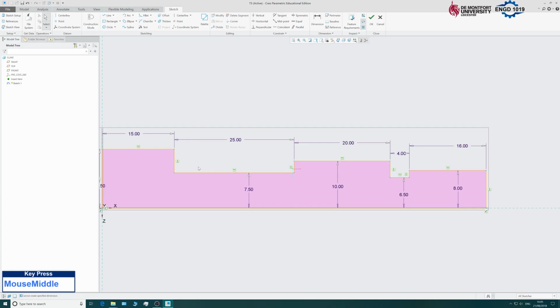So we've got a curved section that needs to have a radius of 20, and then we've got a sloped section down here. And so what's really useful is if we keep these lines here, because they're obviously giving us the overall shape, but if I turn them into construction lines, they'll be there to reference, but then they won't form part of the overall shape.